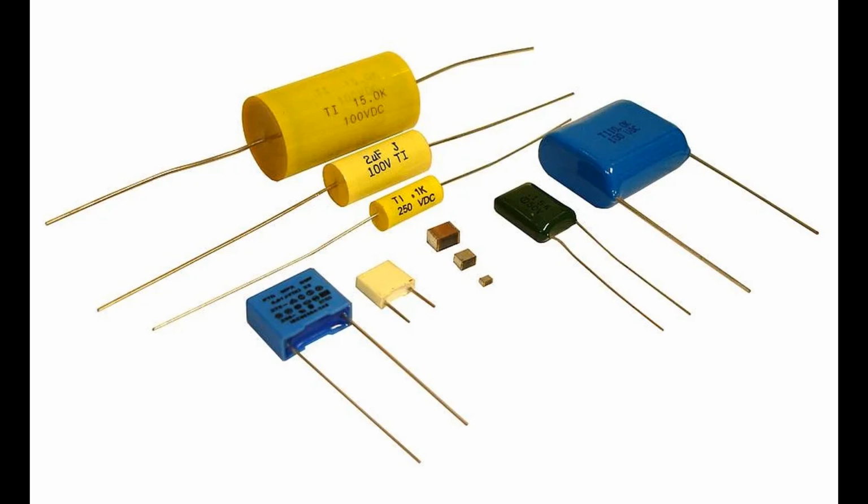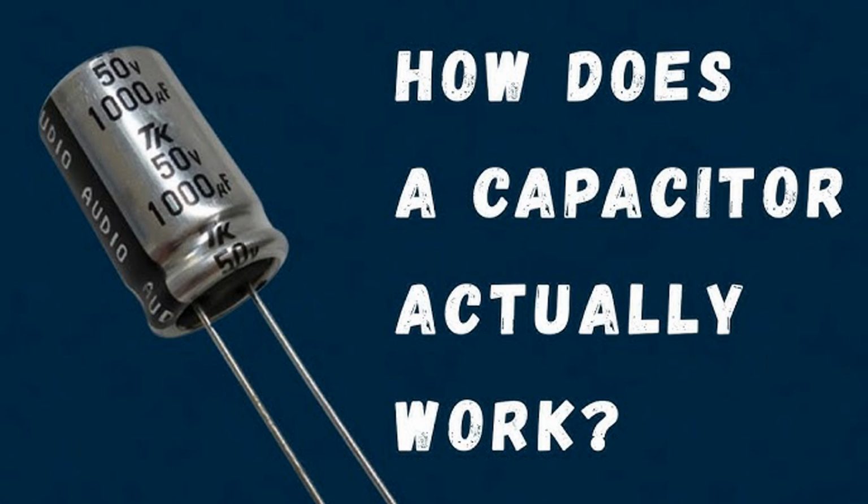4. Automotive applications. Electric and hybrid vehicles. Film capacitors are used in automotive power systems to manage voltage, filter noise, and stabilize electrical systems in hybrid and electric vehicles, EVs. Power conversion and energy storage. Film capacitors help in converting and distributing power efficiently in the drivetrain and battery management systems. EMI suppression. In automotive systems, film capacitors are often used to filter out electromagnetic interference, EMI, and radio frequency interference, RFI, generated by onboard electronics.